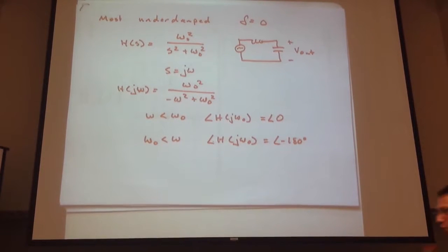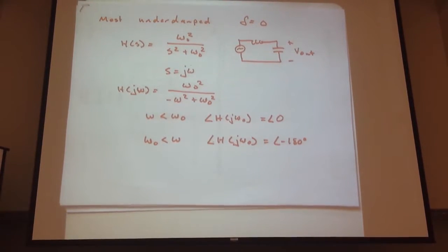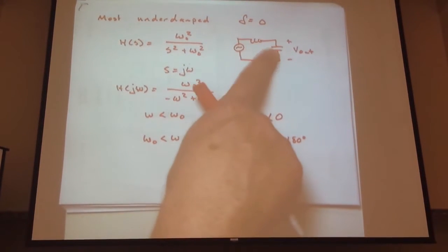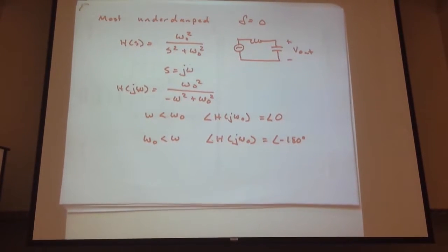Well, at resonant frequency, what's true about the impedance of the capacitor and the impedance of the inductor? They're equal and opposite, so they sum to zero. So how much current do we have in this? Effectively, you create a short circuit from the impedance point of view. Current goes to infinity, and effectively what you have is these guys trading infinite energy back and forth between them.